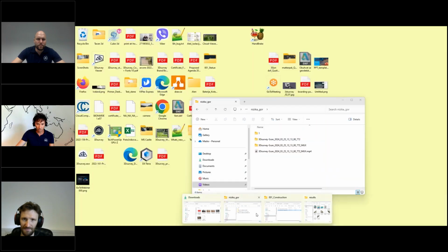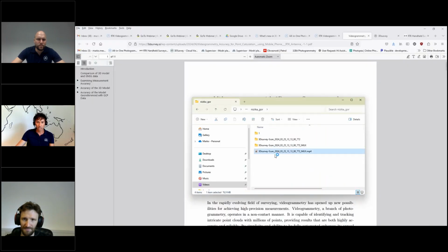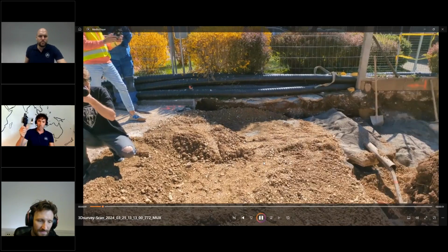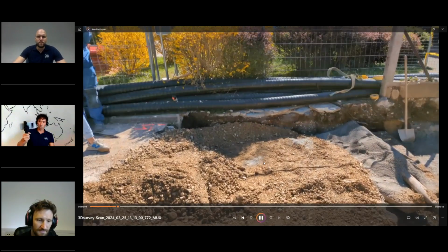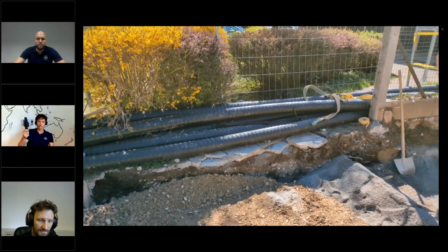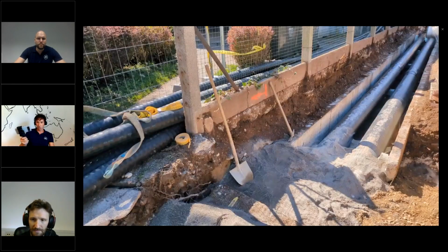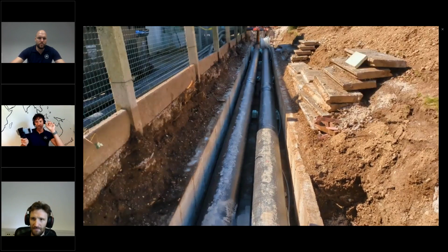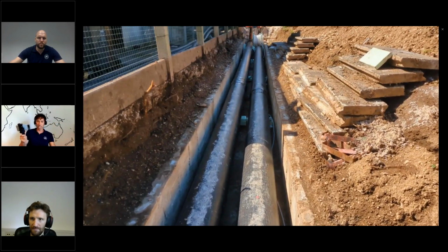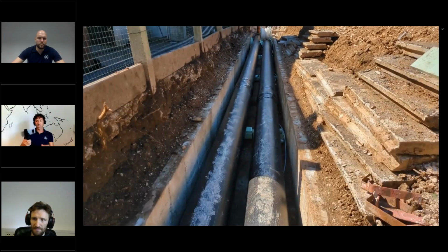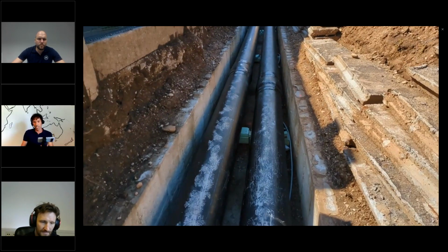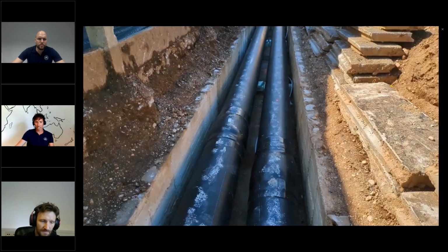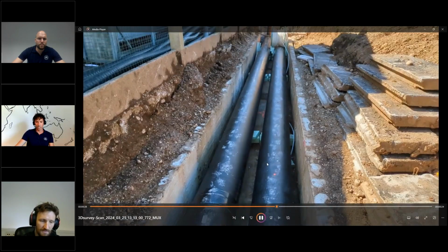So when you are in the field, I think here I have one recorded video. You do the recording of the video with the 3D survey SiteScan app. It looks like so. We eliminate the stabilization of the video. That's why it's a bit blurry, but this later helps with the accuracy. In 30 seconds, you record the video. In this case, we also use an external RTK antenna device, which improves the data acquisition.